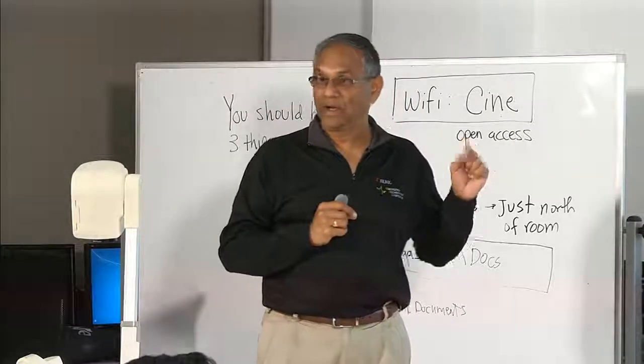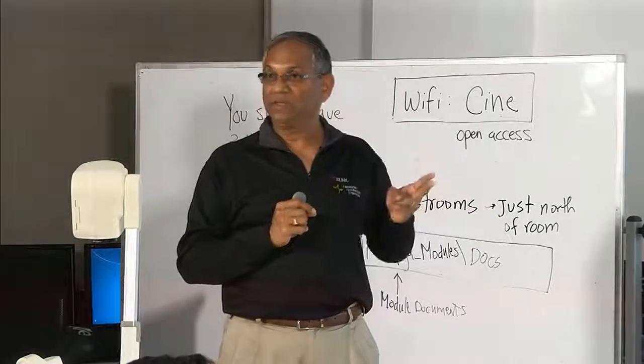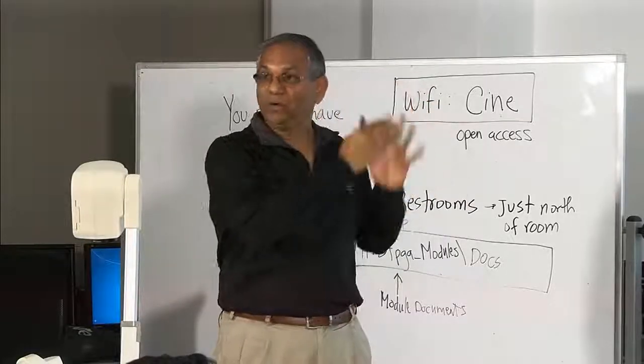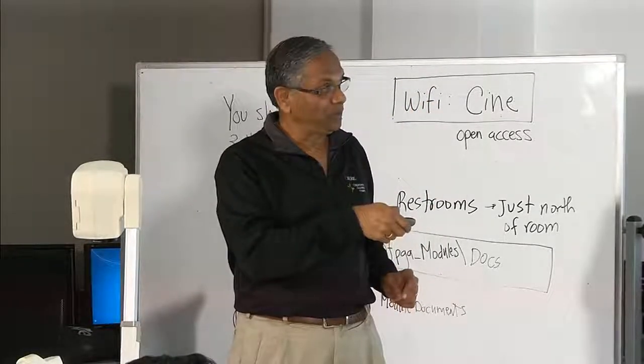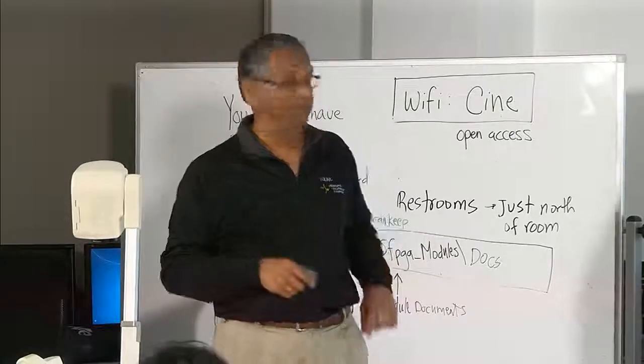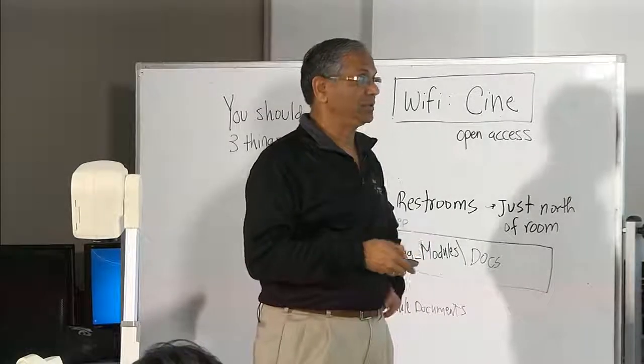And then you can have rising edge or falling edge, but the inversion takes place at the input of the slice, not at the input of the flip flop itself. Okay. So, these are a few things you have to consider.